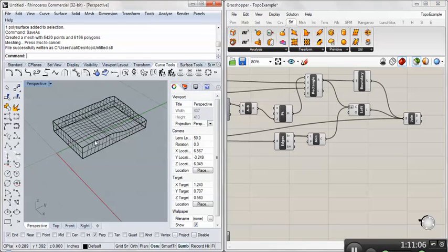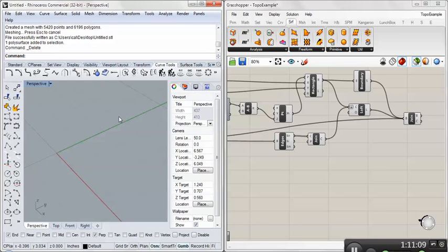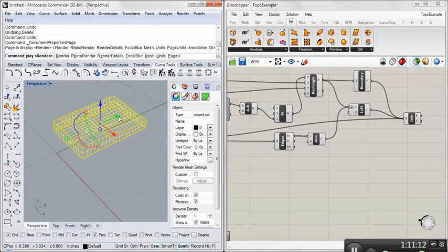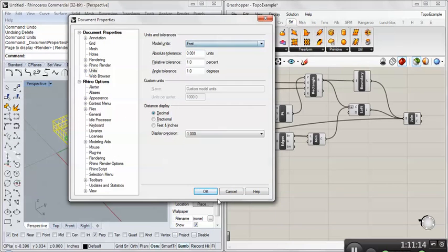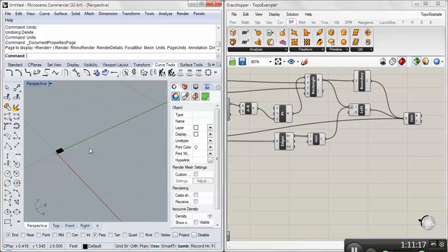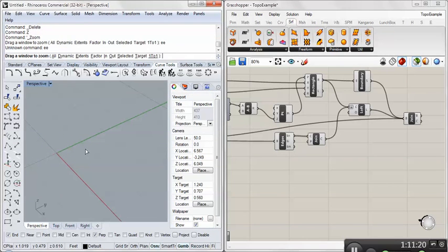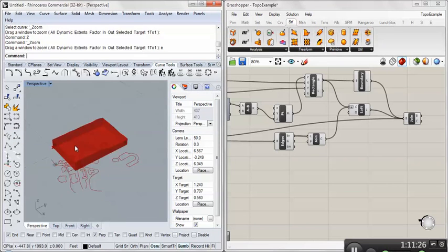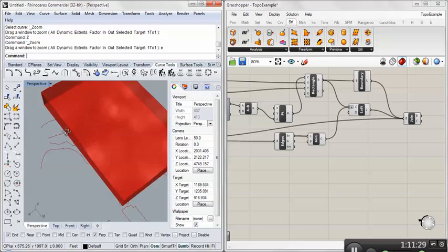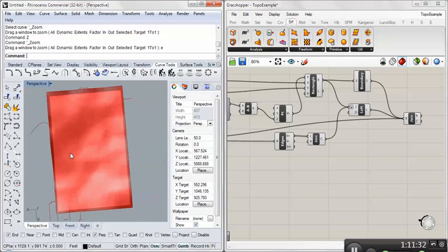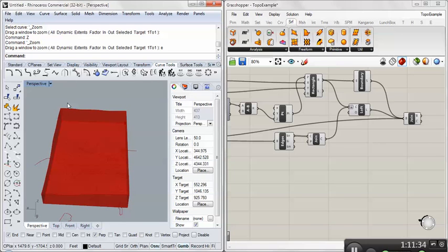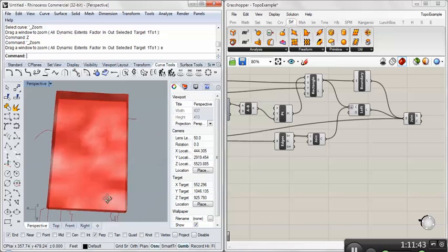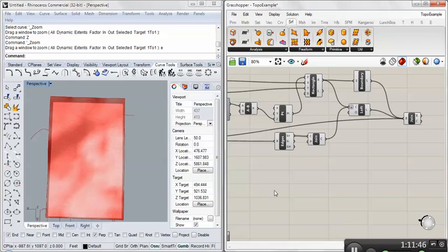Okay, so let's go back here. Units, I'm going to turn it back to feet. There we go. Usually, though, the first thing you do with site is you have the context up on the top, and you also have where you're going to actually carve out, dig your foundation, and put the model. So let's do both of those things, because all of that data is down at the 0, 0. It's easy to move it up to the top surface.